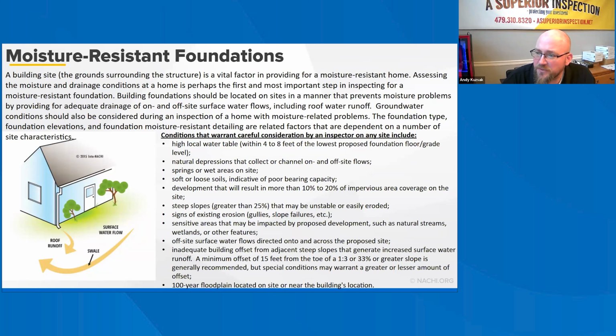Providing for additional slope is a good method to offset future settlement of foundation backfill next to the building, unless the soil is moderately compacted or tamped during the backfill process. That is something that you're going to see oftentimes. I know InterNACHI has a diagram of loose backfill applied to a foundation wall that does settle over time, and then eventually the ground is not pitched away from the home. It actually is pitched towards the home, and then water will funnel towards the footer and the foundation.